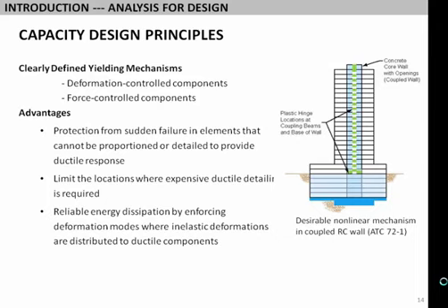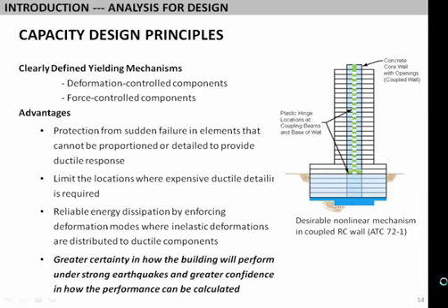And I think with new buildings, you have the opportunity to do that much better than, in contrast, existing buildings when you're rehabilitating. But from the standpoint of analysis, another big advantage of capacity design is that it really makes our analysis easier, okay? Because if we have well-controlled ductile elements and we know where they are, we have a better chance of modeling them. And again, the messy force-controlled elements, which we're shielding from nonlinear actions, we handle elastically. This is in contrast to modeling an existing building, where you just have to model the building that you're dealt. So in design, think about how that can really help your analysis, and the nonlinear analysis gives you more confidence in what you're analyzing.